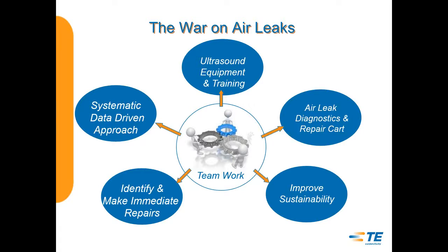We came up with an air leak diagnostic and repair cart. So while we were out wandering the 200,000 square foot of floor, we had everything we needed at point of use, ready to make those repairs. We also did a lot of work for improving the sustainability of it. So while we were out there fixing air leaks, we tried to pay attention to how we can reduce the number of fittings, how we can improve the fittings.